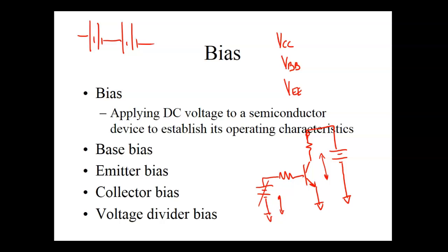Switches won't do that. So if I came over here with our switches, and we showed y'all that the other day, this is a typical switch where we put our load up here. So here the primary source is on the collector. So this would be what we call collector bias. I bring my signal in here. If I try to put AC on this, while it's going positive, this would put a positive right there, and the transistor would cut on. But when it goes negative, the transistor wouldn't do anything. In fact, we could actually damage it because of the reverse breakover voltage.